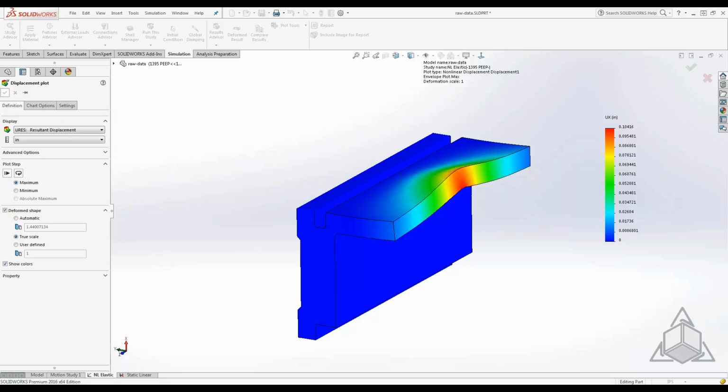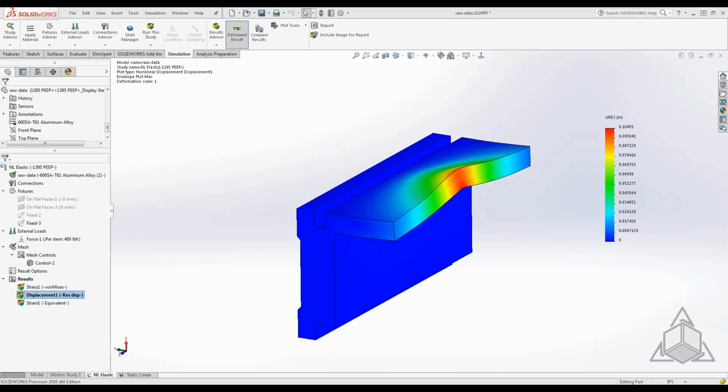Which model to use for nonlinear material like rubber and PTFE? There are a few different model types underneath that in the material property window. There's hyperelastic, there's non-elastic, there's plasticity. I believe there's 6 different model types. So we can actually look and see. If your material is hyperelastic, obviously you would want to pick a hyperelastic model type.